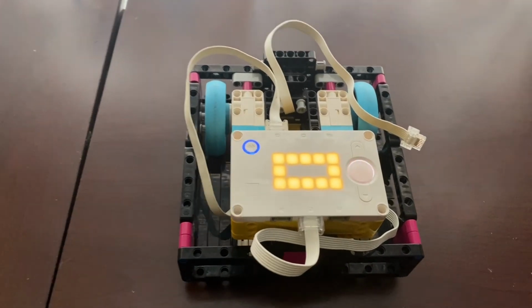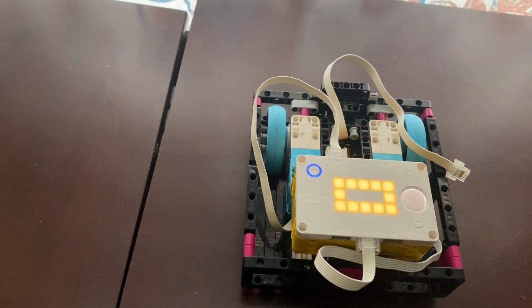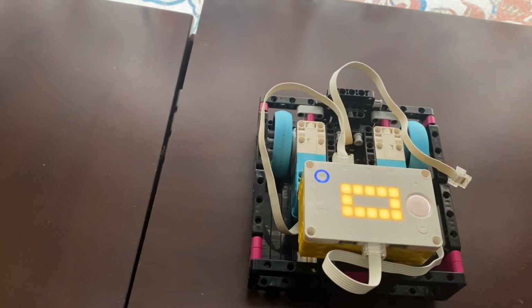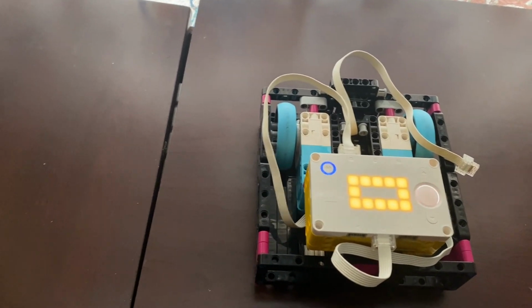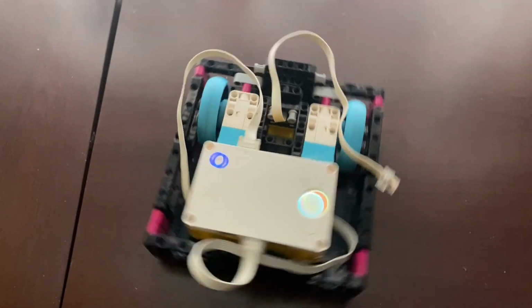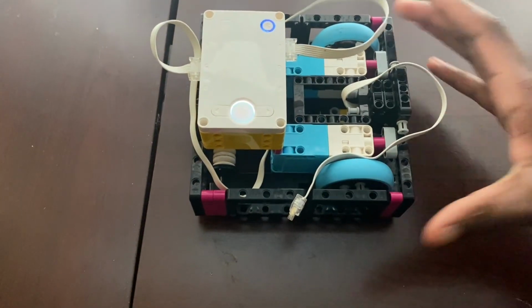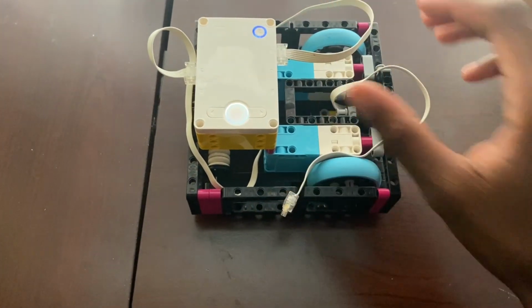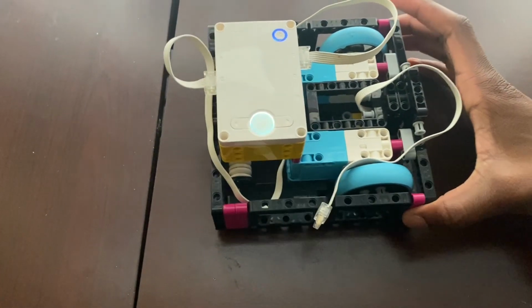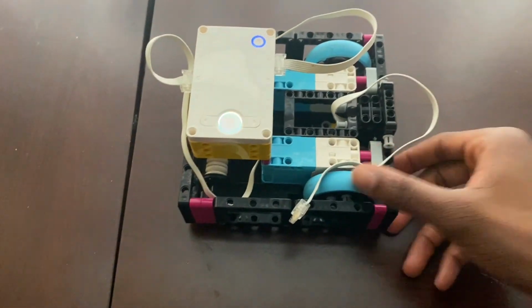Alright, so the first thing I'm going to show is the robot turning 90 degrees. I have the program pulled up, the same one we just made, and I'm going to type in 90 here, and play it. So it moves pretty swiftly, pretty smooth, and turns to that 90-degree position. And you can see that as it's turning, it's slowing down over time, which is that P controller. You also notice that it's holding its position. That's what that block does in the program.